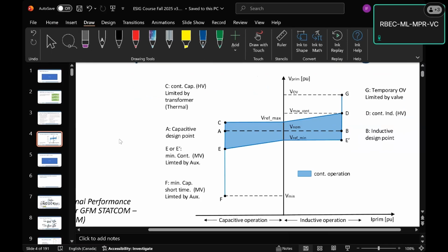So the thing that's changing now is the data centers, right? And suddenly we're going to have, we'll talk a lot more about this on Wednesday, a lot more trouble with voltage control. And so STATCOMs are coming in and they're very big. In the last couple of years, this is even pre-data center, 2 years ago, we did testing on a 2 times 400 MVA in California, but lots of them are hundreds of megavars, I would say.